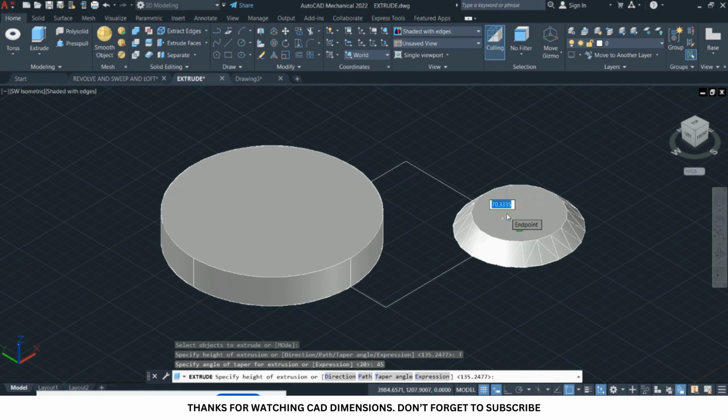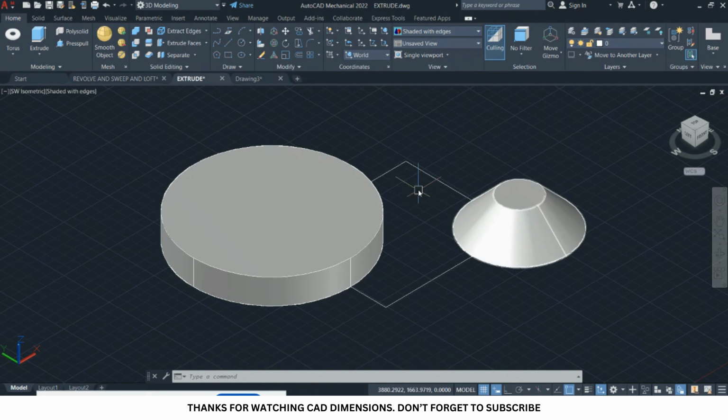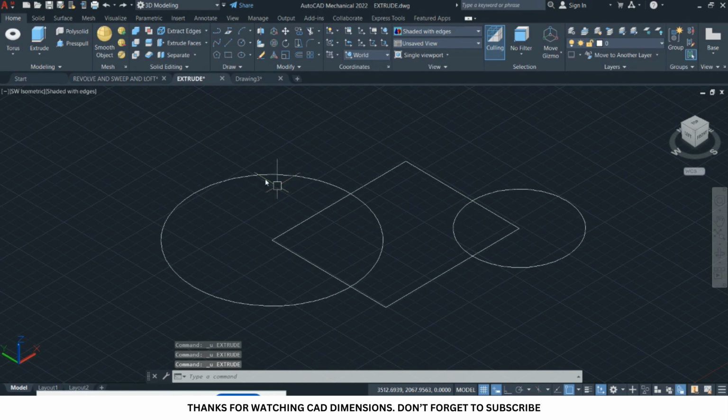So that means that you can actually create an extrusion with respect to a taper angle in this orientation, with what you see on your screen. Okay, so I specified 45, and that is the reason why it's looking like that. Okay, so this is the taper of the circle in extrusion. Okay, control Z, control Z, control Z.